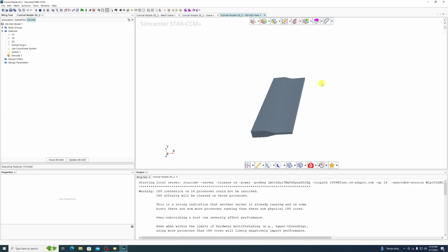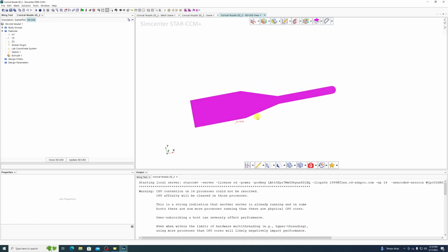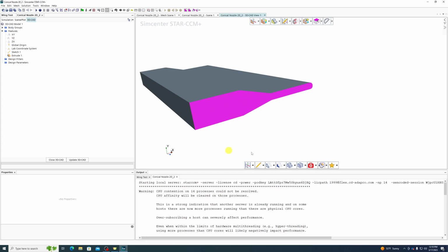So a really long aspect ratio rectangular nozzle, except it doesn't take into account any of the three-dimensional effects. So every slice of this nozzle looks the exact same. So we don't bother simulating all of them. We just simulate one of them, the very slice on the very end. Now this isn't obviously quite our nozzle. I didn't make this quite symmetric, but you get the idea.